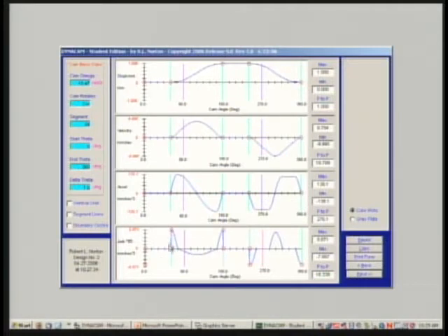There are 2 circles at the same value. This indicates there are 2 values simultaneously, indicating a discontinuity. So this is acceptable in the jerk but would not be acceptable here in the acceleration, the velocity, or the displacement. So I want to see 1 circle at each of these interfaces down through the acceleration.